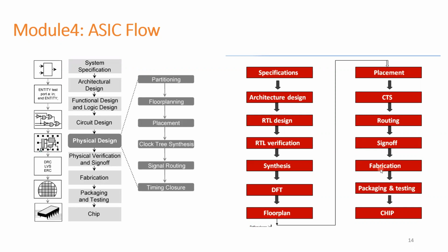Once the fabrication is done, the packaging team will do IC packaging. You might have seen somewhere in the motherboard or in PCB, there will be black packages. That will be done by packaging team. Once that is done, the testing will be done by testing team. So the post silicon fabrication testing process will be done at this stage. So this is what they will do. Whatever the DFT scan logic is inserted during the design process, that logic will be used during this stage.